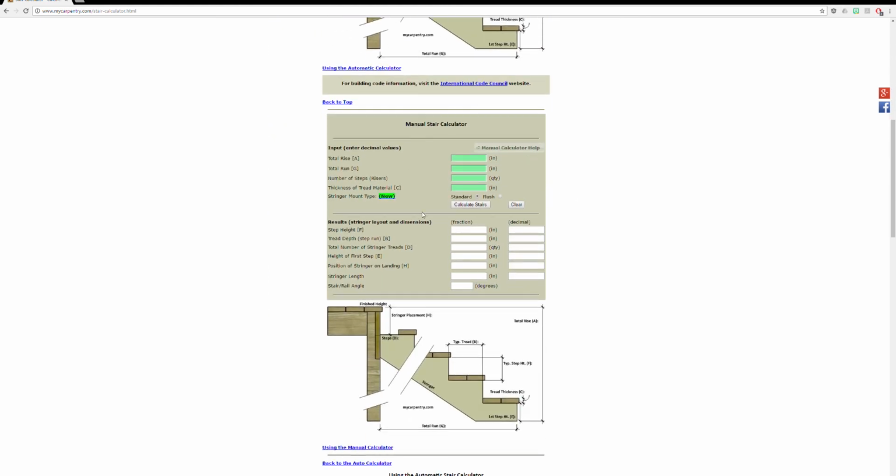I already know that my stairs are probably going to be around 10 inches of rise. So I've already kind of figured out that I think I need 6 risers here. And if you look over here, this is the riser, this little rise right here, and this is the tread, these guys right here. So the overall rise over run, this is the total rise over here, and this is the total run. But then we got these little rises and little runs. So the little rises are the risers, and the little runs are the treads.